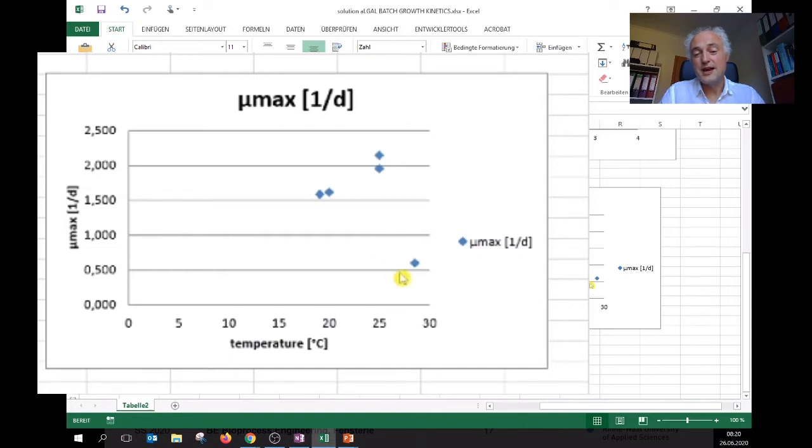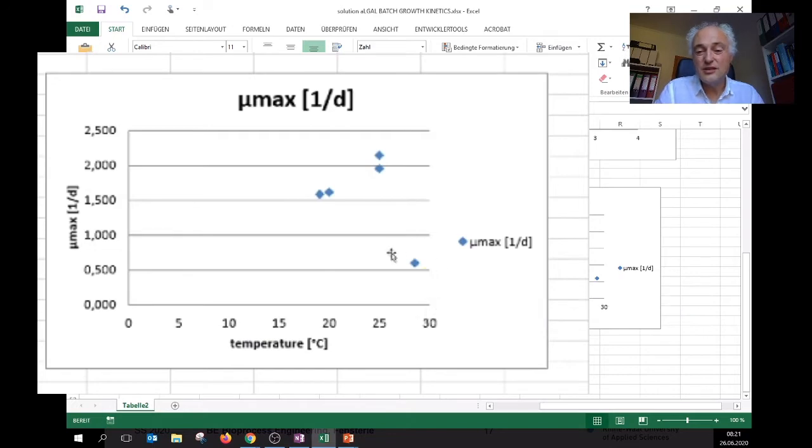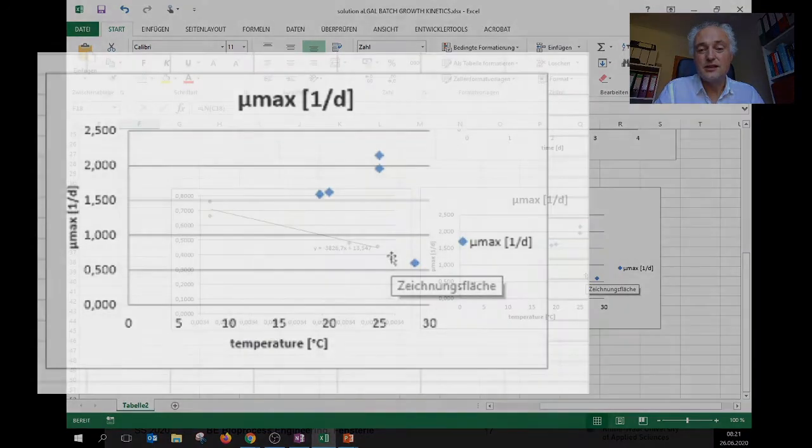This drops out. And this is, again, not maths what you're doing here, it's bioprocess engineering. The reason is that these are algae, and based on my data, either it's an incorrect measurement, or more likely, in this temperature area we're above the optimal specific growth rate, and the growth rate declines. So we take out this value for the calculation.